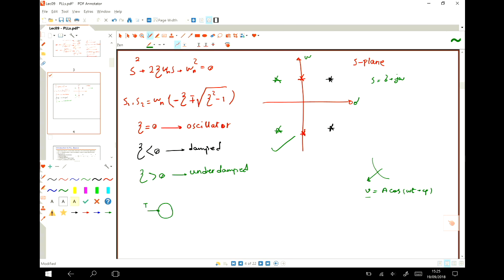So in the transmitter, your IF signal or your baseband signal is multiplied by one LO, and then this RF comes from your transmitter to the receiver, and again I need to multiply this by LO to get the IF. This is how a wireless link works. But the problem is this LO is generated in the satellite, and the other LO is generated in my circuit. So they are different.